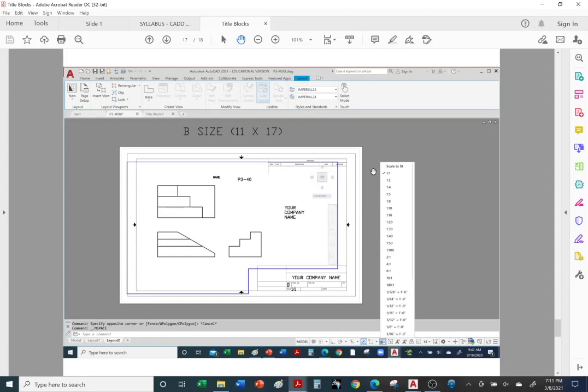And now typically you'd want to go with 1:1 as far as scale. But if this part is too tiny, then you want to go with something like 10:1. So if you're doing some electronic part, let's say for a phone, a small piece, you may want to increase it to 10 times. Use 10:1. Or maybe your part doesn't fit the sheet. If it's too large, a good example is maybe the size of your laptop or your computer, 1:1 is too large. You can go to half size or quarter size and so on. Try and use one of these standards.